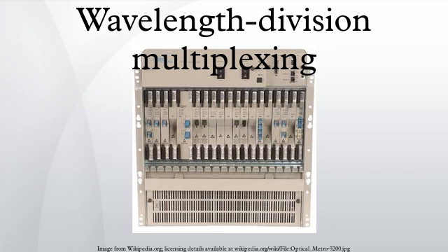Reconfigurable optical add-drop multiplexer. As mentioned above, intermediate optical amplification sites in DWDM systems may allow for the dropping and adding of certain wavelength channels. In most systems deployed as of August 2006, this is done infrequently, because adding or dropping wavelengths requires manually inserting or replacing wavelength selective cards. This is costly, and in some systems requires that all active traffic be removed from the DWDM system, because inserting or removing the wavelength-specific cards interrupts the multi-wavelength optical signal.